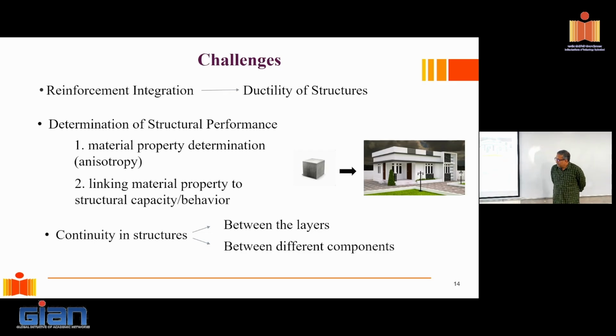And then the other challenges, like in any concrete structure or even in precast structures, is continuity between structures or structural elements. Here I have an additional complexity: when I talk about continuity in structures, I have to worry about continuity between the layers. Layers are simply printed, deposited one on top of the other, so I have to make sure that stress transfer can take place between the different layers. That in itself is a challenge. And then between the different components, suppose I print one component and another component, how do I integrate them so that they act as one structural unit? So these are all the different challenges, and people have come up with clever solutions.